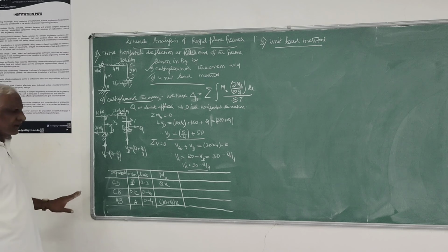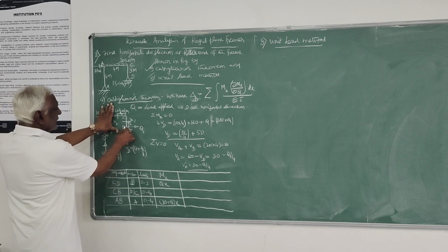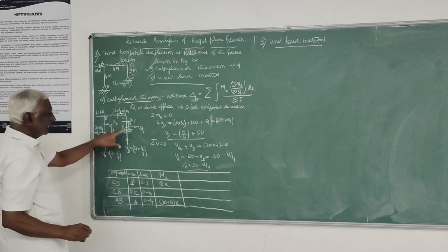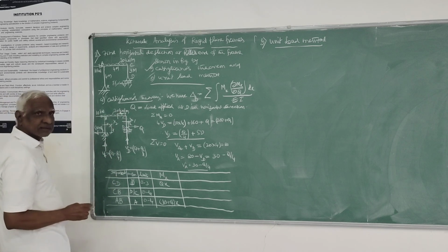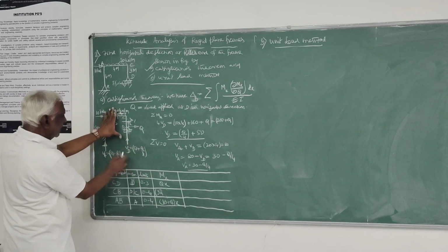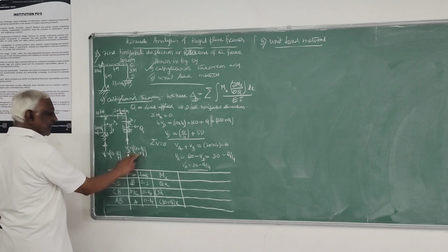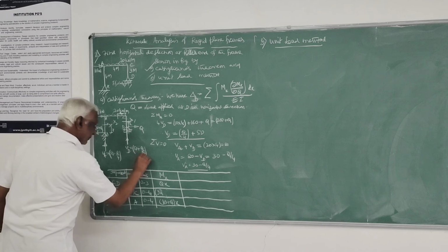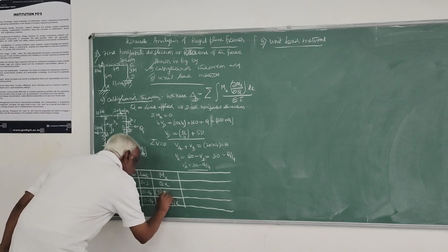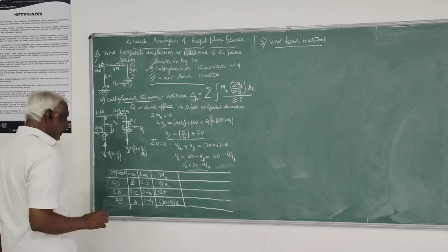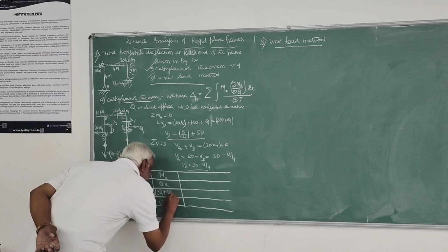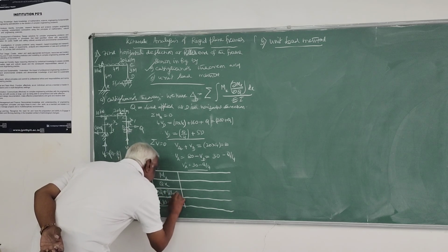Then, in this middle member, carefully you have to see this sagging, because this q will give a moment, again inside sagging, that is q into 3, 3q. Then due to this Vd into x, that is 50 plus q by 4, so 3q plus 50 plus q by 4 into x, that is 50x plus qx by 4, plus 50x.